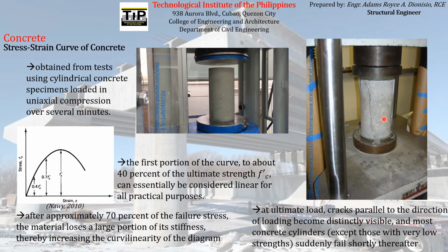At that point, cracks parallel to the direction of the applied load, which is the vertical direction, usually become visible, and then the concrete will suddenly fail.